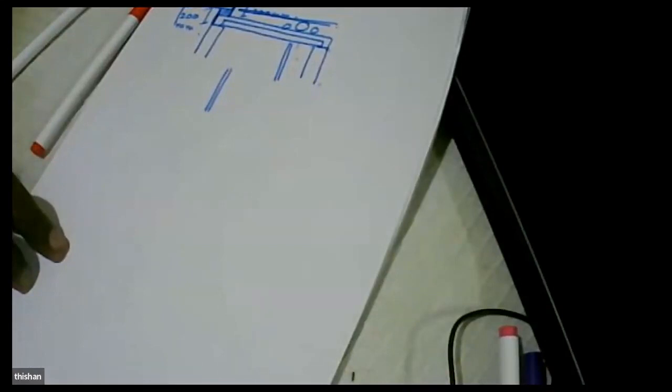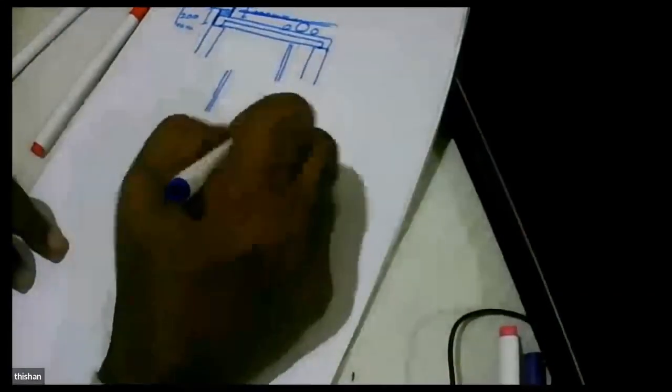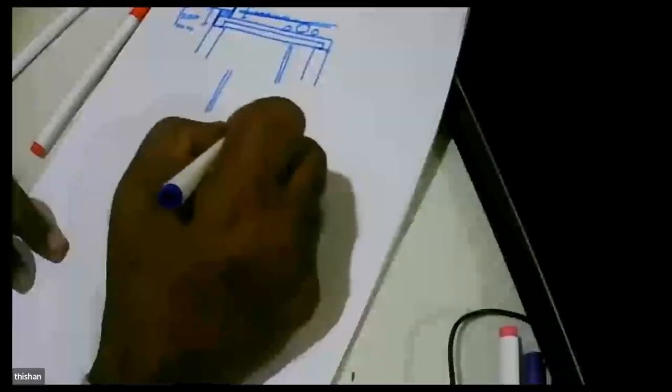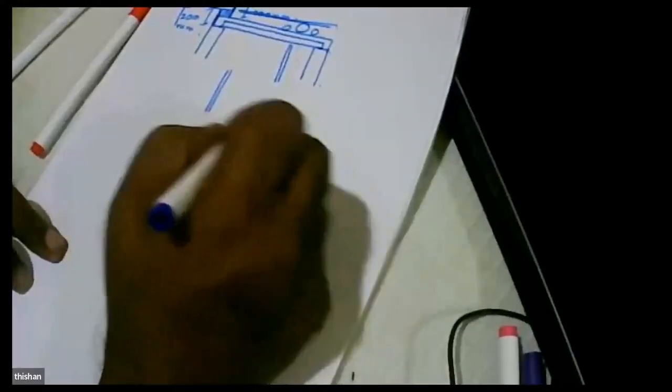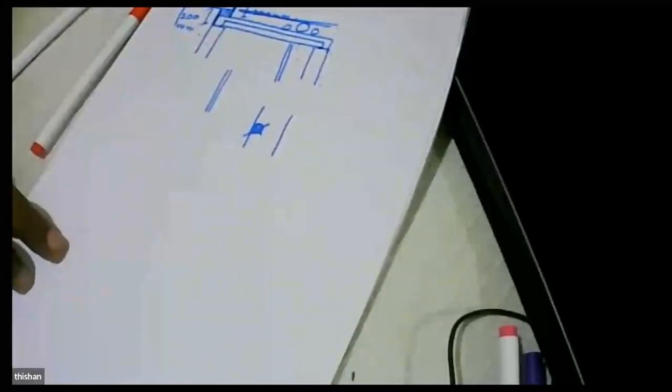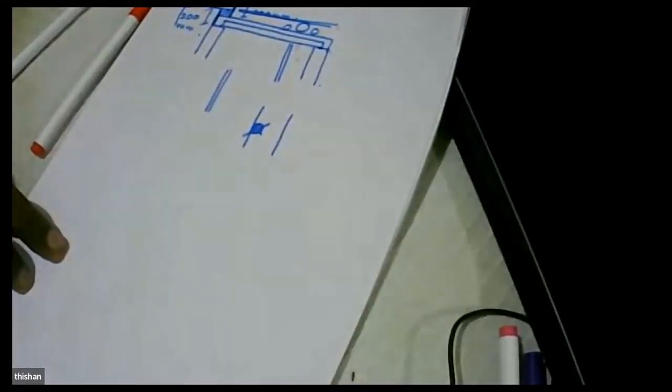In any load bearing wall we should not have chasers in the horizontal direction. That is not a good practice. So we have to plan the services in such a way that we keep most of the chasers as vertical as possible, because the effect of a vertical chase on a wall is minimal. So it will not be a major problem.